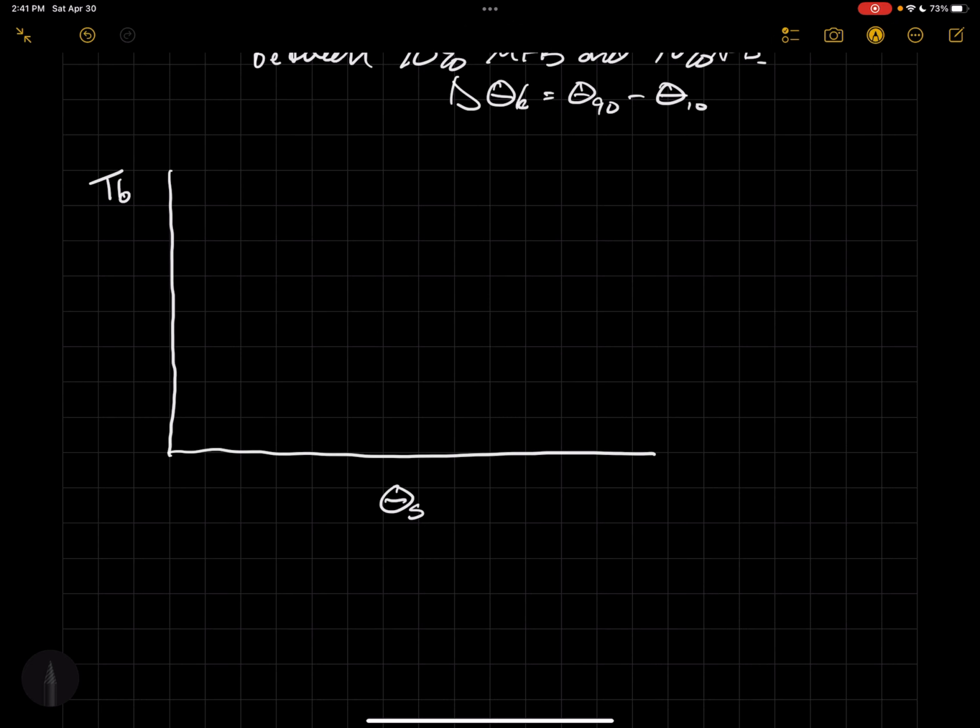The engine is, say, operating in a steady state condition, right? And then I change my spark timing to a different spark timing, and now the engine is making a different amount of torque cycle after cycle in a steady state fashion. And so when I plot the brake torque versus spark timing curve, what I'm showing you is the torque value as the spark timing changes for a given steady state operation of the engine.